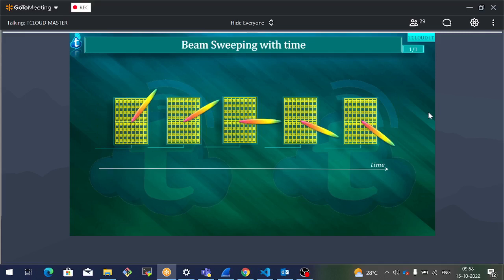So what they decided to do is allocate some kind of index to these beams and help the mobile equipment itself detect which beam is suitable for its operations. That information will be useful at a later point in time when the mobile is dealing with various other things. How, we will see later. But we can send this common channel related information into these beams and sweep them throughout the 360 degrees of your geographical location in terms of direction.